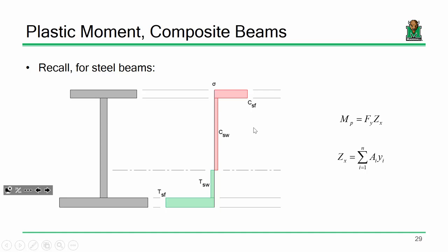We looked at the maximum capacity. We started off looking at the maximum flexural capacity of just a steel beam by itself. And we recognize that we have a term for that. We call it MP, the plastic moment capacity, Fy times Zx. Find the point where the compression equals tension, find moment arms, sum moments. There you go. Sound good, right?